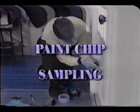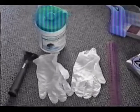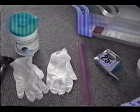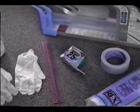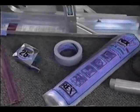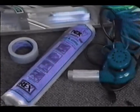Let's look at the tools you'll need to assemble for paint chip sampling. You'll need a sharp stainless steel paint scraper and disposable wipes to clean the scraper. You'll also need several pairs of non-sterilized, non-powdered disposable gloves, a ladder, a ruler or tape measure, and a roll of plastic sheeting. A heat gun is recommended to soften the paint.